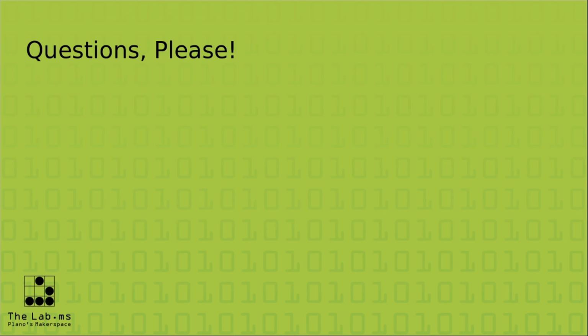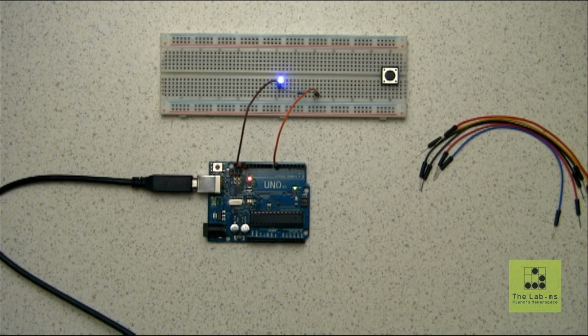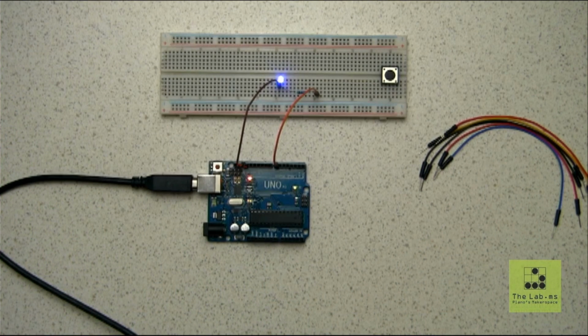Oh, yes, I wanted to circle back to the question about interfacing with external things like audio equipment. So the Arduino itself doesn't do a whole bunch. Pretty much anything you want to do, you're going to need to connect some sort of other board. Arduino uses the terminology of, I'm going to get this wrong, shields. Yes, okay. Raspberry Pis use hats and Arduinos use shields. And you can get an audio shield for the Arduino.